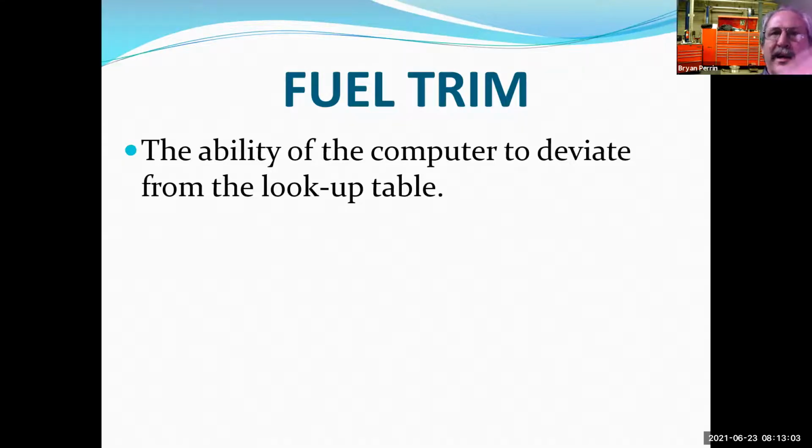So it allows you to not get buried in, it has to have a vacuum leak, or I put 3 mass airflow sensors in it, or I put 2 fuel pumps in it. It keeps you out of just beating your head against the wall. Well, hold on a second. Let's think about what the computer's doing. And more importantly, how is the oxygen sensor operating with what we're doing? Is it still oscillating? It looks normal, or it's stoichiometric, because I might not have a gas analyzer, so I need to use the O2 sensors for that, which means the computer is doing the correction correctly.